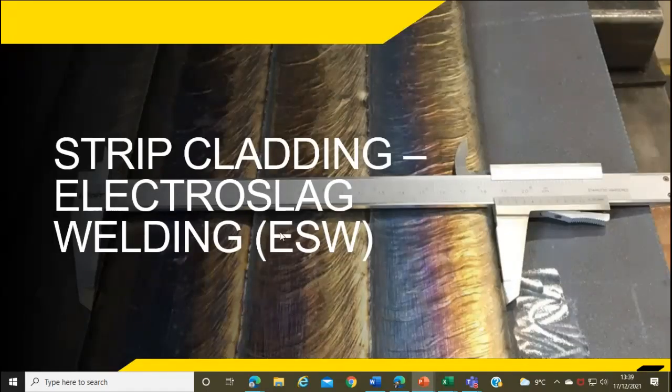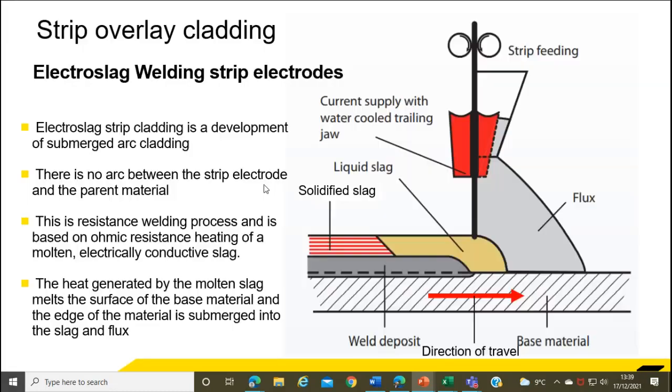Now, what's the difference between that and electroslag welding? Well, on the face of it, it looks very, very similar. And the biggest difference that you can see immediately is that the flux is just being fed one side. So the direction of travel is again left to right, and you see that the flux is only put in front of the direction of travel. The big difference with this is that the flux is an electrically conductive flux. Because of the minerals that it's got in it, it makes it electrically conductive.